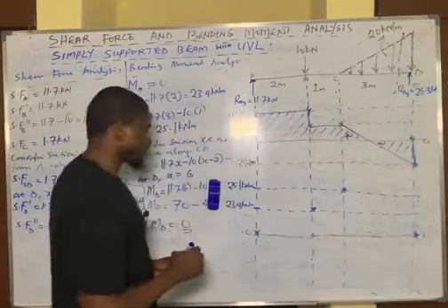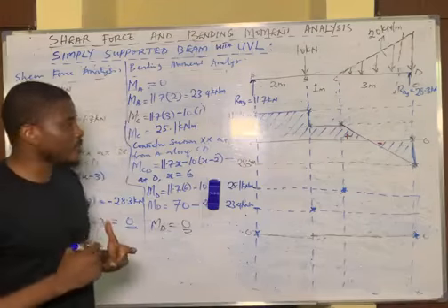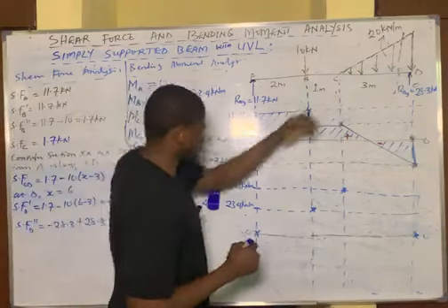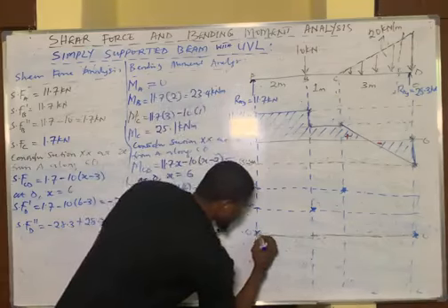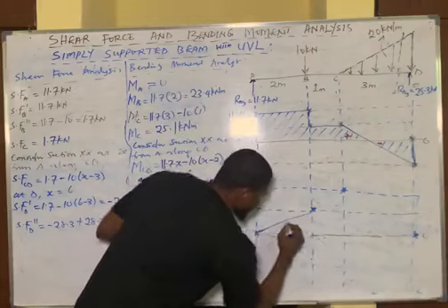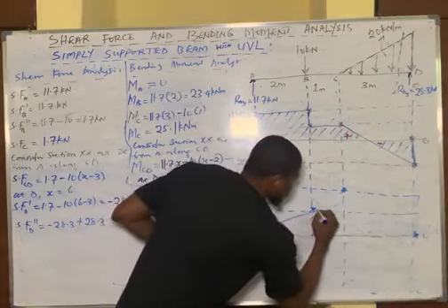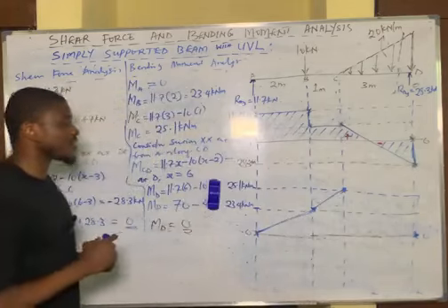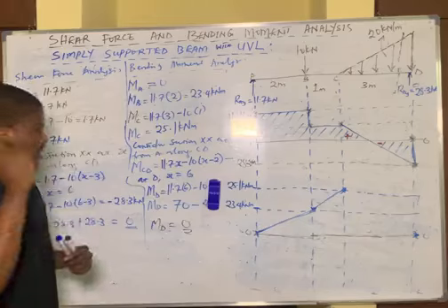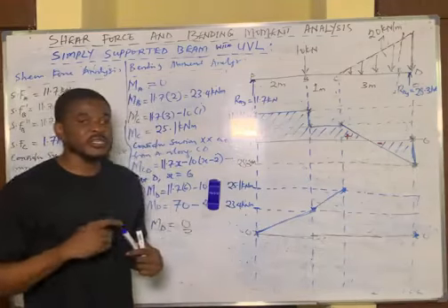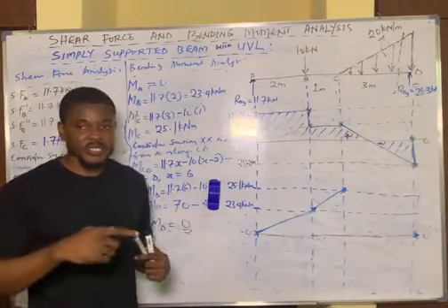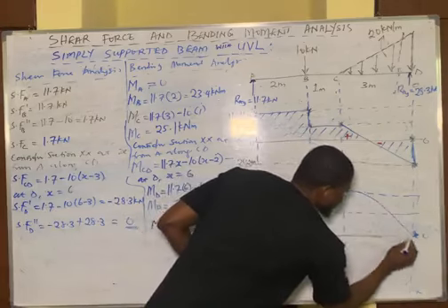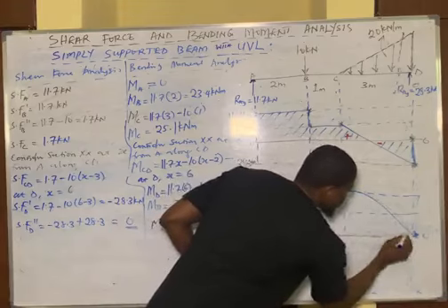You simply asterisk. Now, the moment diagram for a point load is simply a slant line connecting each of the points. So I have point loads up to point C. So simply a slant line, connect from here to this with a slant line. Connect also to this with a slant line. Now, between C and D, we have a uniformly varying load, right? The bending moment diagram for a uniformly varying load is simply a hugging curve, like a curve that is hugging. So you simply draw a curve and you have something like this between C and D. So it's basically a curve.